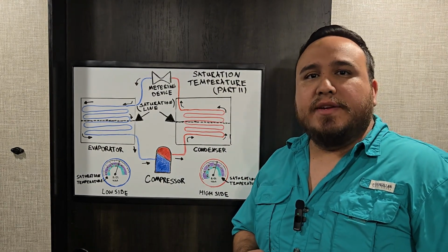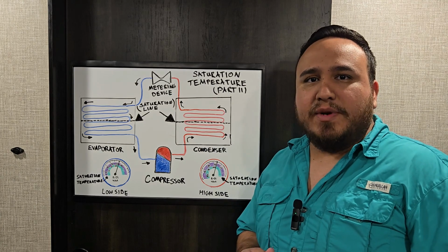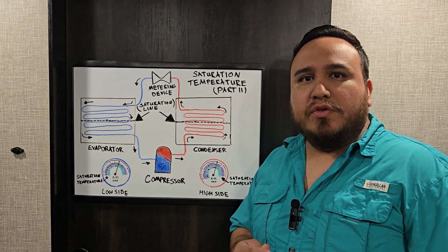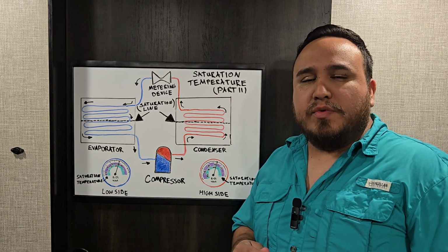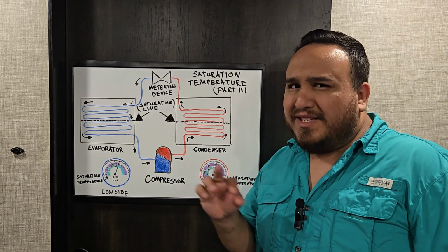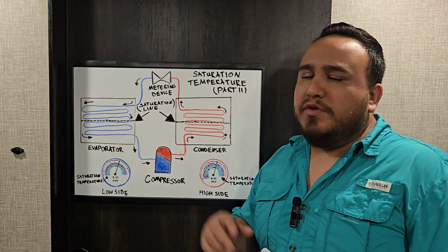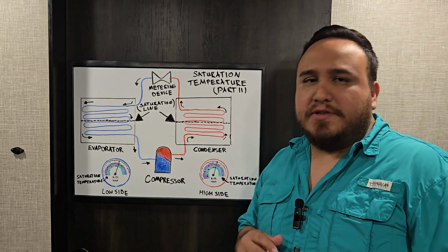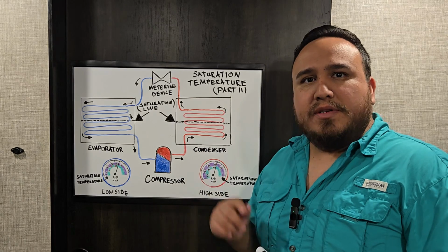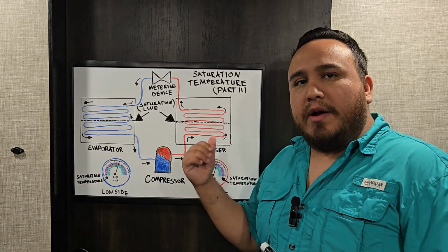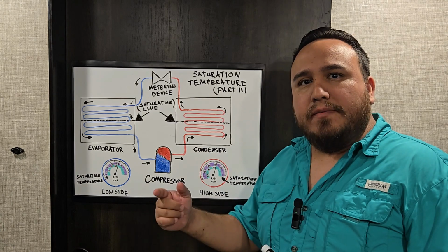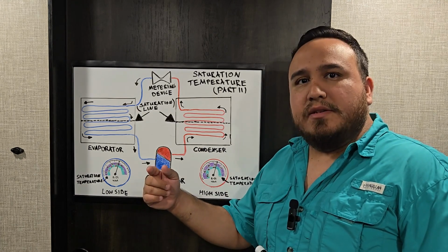In this video, I want to talk about the second part of saturation temperature. If you do not know what saturation temperature is, I encourage you to go to the previous video that I made. That's where I start talking about what saturation temperature is and how I use an example of water to demonstrate how it works. On a brief note, remember, saturation temperature is where, in my air conditioning system, the refrigerant is both in the state of liquid and vapor in the same place at the same time.